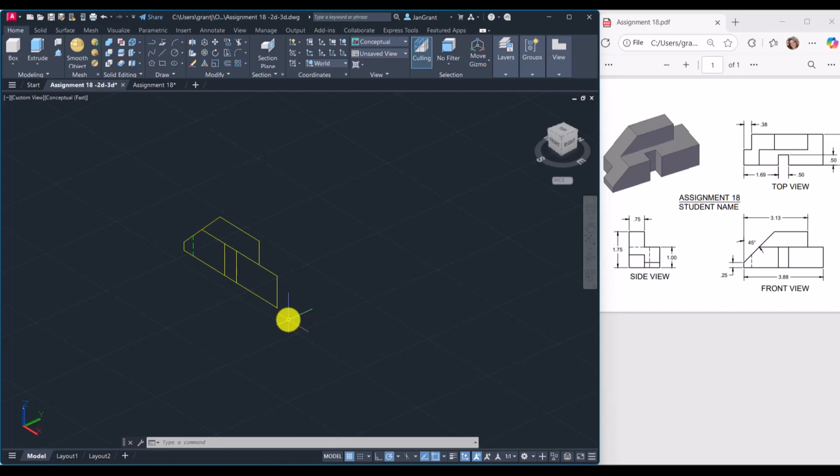So I decided in this video, not sure why, to rotate the 2D geometry so that we could press pull out this way and out the other way, since this is like the midpoint of a cut through the middle of this model. So we won't be able to use press pull until we get this UCS icon over to this corner and rotate it up. So we can click on this UCS icon, click on the little box right there. We're familiar with this. Click and put it right there. Now you can see that the XY is not straight up. So I'm going to click on the Y and pull my mouse up and click on the top line right there. You see what it does?